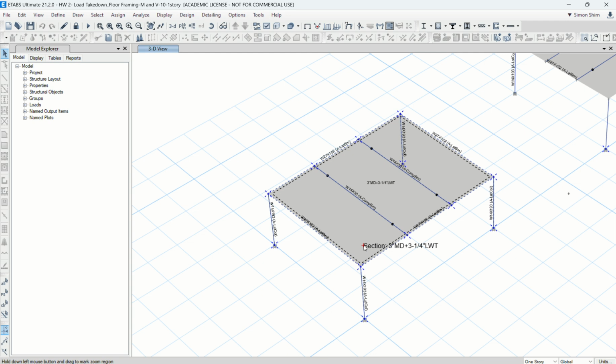Then what is a moment connection here? We need to provide additional top and bottom restraint. So typically we need to provide another plate, bolted and bolted. And somehow we need to provide this in a couple of different ways. We need to bolt it and provide the top and bottom flange to create the restraint for the rotation. So additional connection plates and bolted connections are needed to make the moment connection. But we'll get into that.